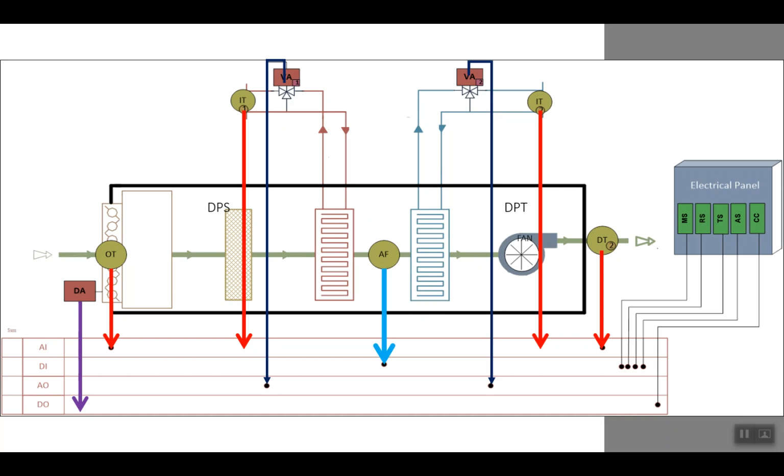But in some cases the outside temperature doesn't drop so much, so we need less, and we can control the valve to save energy and provide the adequate output according to the closed loop controller. So these are continuous valves, because they control between 0 to 100%, and they are controlled by the BMS from an analog output, a signal between 0 to 10 volt.